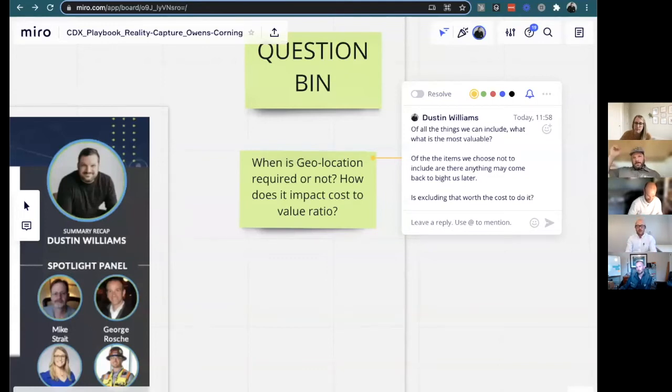So I was getting at the error over that entire project. If you looked at a grid and you look at your existing steel, where is that error? Did the bays creep up a quarter of an inch in that direction, or did they creep up an inch in the other direction? How is that error distributed? So the control helps you really align that and know, oh, because I have control, my grid is aligned, my scan's aligned, and this whole bay over here is actually off. And now you can know that that's the one that's off in comparison to your documents.